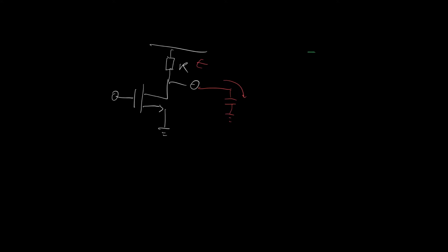An ideal FET would look like this. We have one voltage-controlled switch here, and we have another voltage-controlled switch here. This is the output, and depending on the input, if the input is a logic 0, then we want this switch down here to be open, and we want this switch up here to be closed.